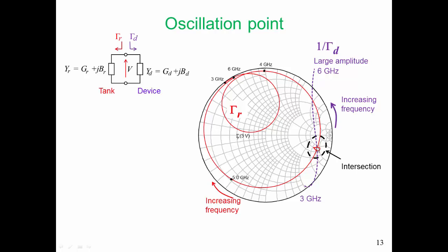And you may wonder why we can build oscillators at all if there has to be an exact point. Well, it turns out that as our amplitude is increasing in an oscillator, the harmonic content is changing very slightly. So if we get close to this point, our harmonic content in the oscillating signal is going to shift just slightly so that we lock in on that point.